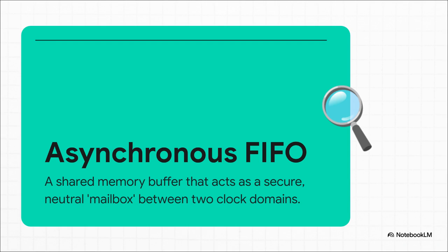Okay, another really common and powerful solution is to avoid a direct border crossing altogether. Instead, you build a sort of neutral, demilitarized zone in between. It's a shared memory buffer called an asynchronous FIFO, which stands for first in, first out. Think of it like a mailbox. The sending domain drops off data in the mailbox using its clock. Then, whenever it's ready, the receiving domain comes along and picks up the data using its clock. They never have to talk to each other directly, which completely and safely isolates the 2 time zones.